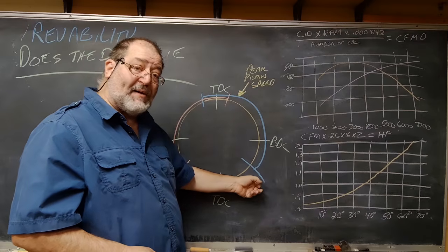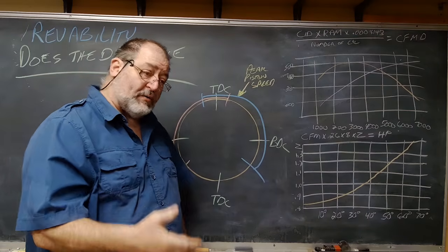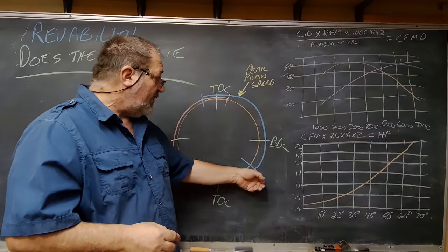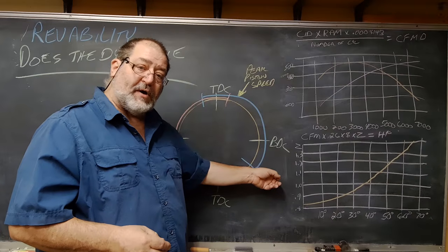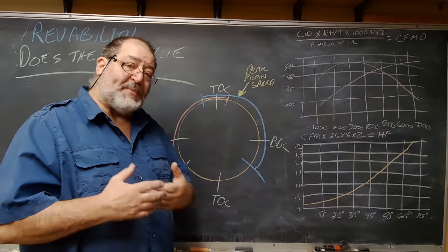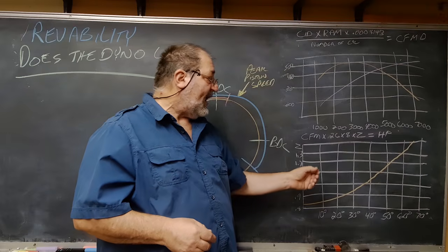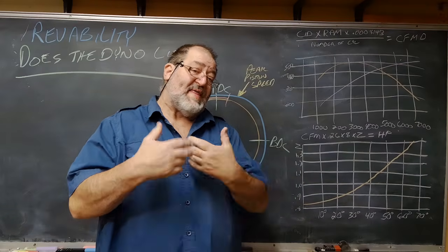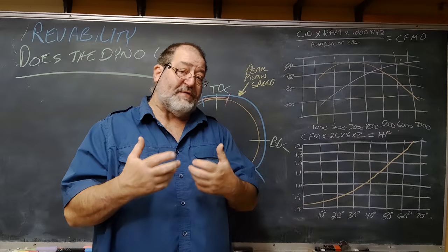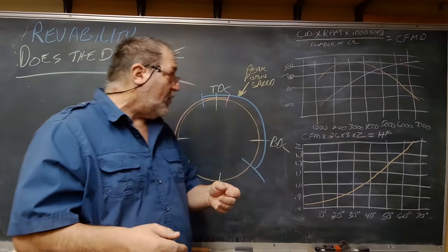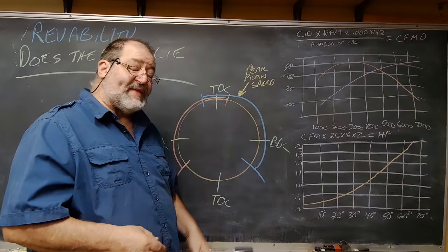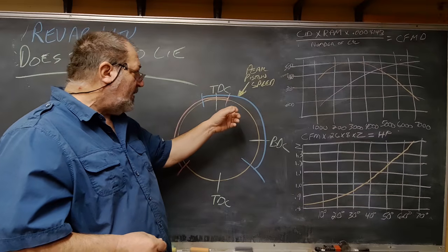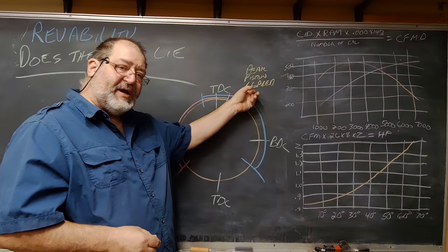This is your initial fill, and that's the feeling of the motor just going, because as the piston comes down, this is where it's initially drawing from. This is inertia ramp. This is after the piston is down and coming back up, and you're using airspeed to fill the cylinder down here. So that becomes about cross-section, airspeed, and inertia ramp. That initial feeling, that revability, the ability of the motor to just take off and go, is about fill at that peak piston speed. And the more restricted you are, the better exposure you need here.